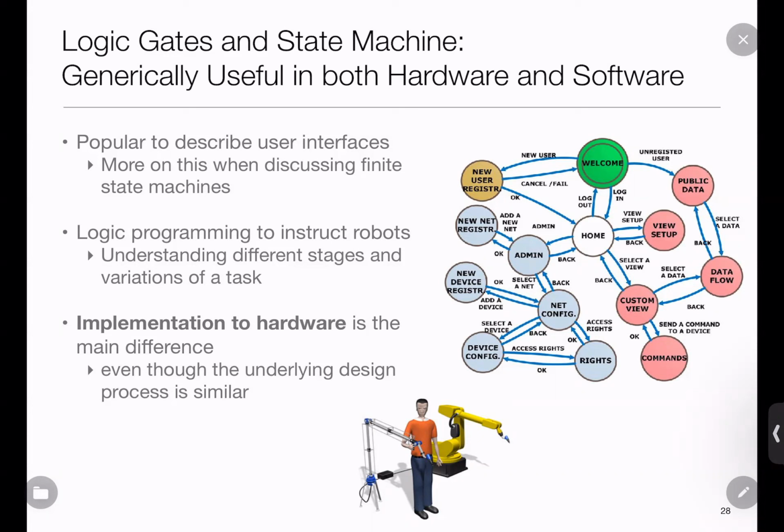There are a couple of different things. Hardware is different in the sense that instead of a processor and things running in lockstep on it, here we often have to worry about lots of things happening in parallel. So it's a very different mindset. The second thing is that timing plays a very important role in hardware. When is what happening, in what sequence?